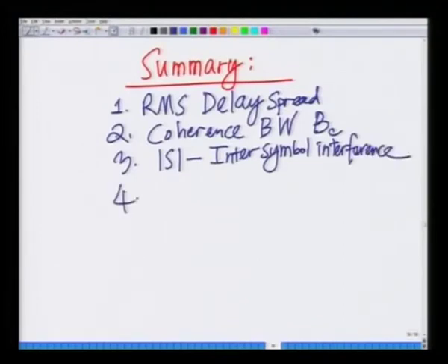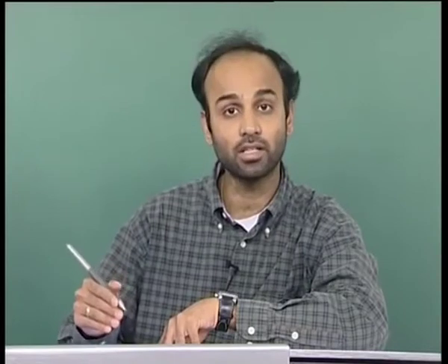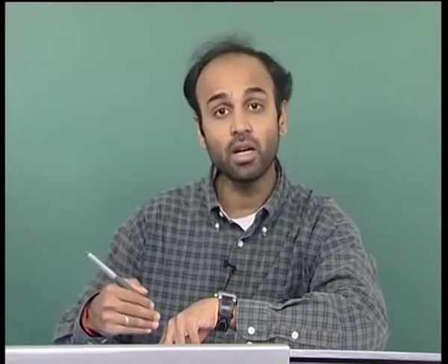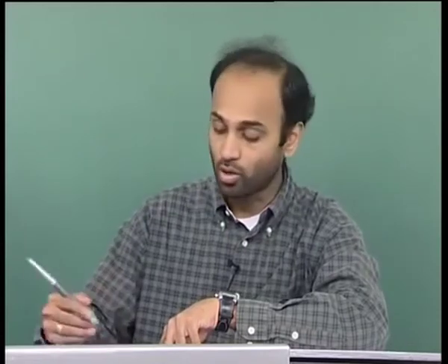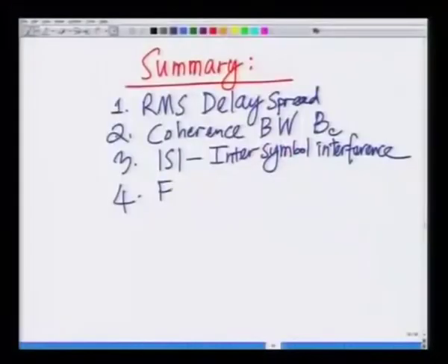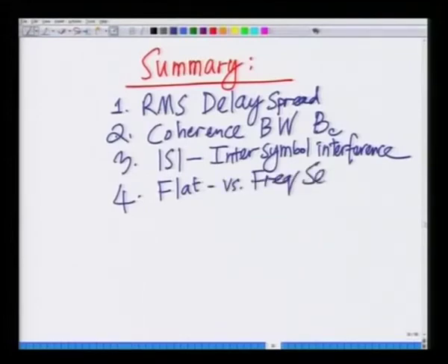We said that if the delay spread is greater than the symbol time, it results in inter-symbol interference, and in the frequency domain it means that the signal bandwidth is greater than the coherence bandwidth. So, we looked at the concept of flat versus frequency selective fading.